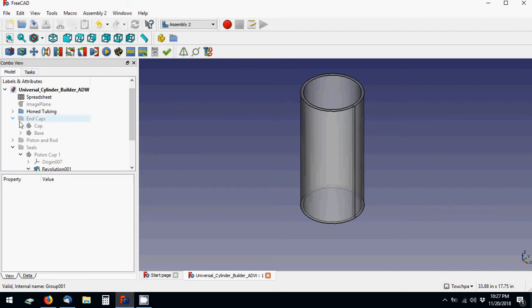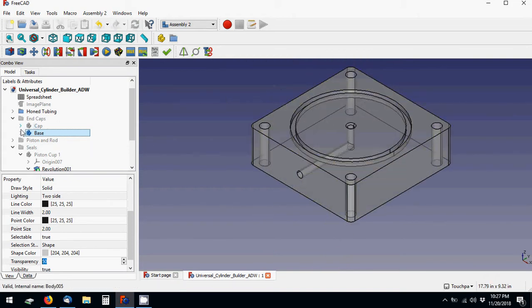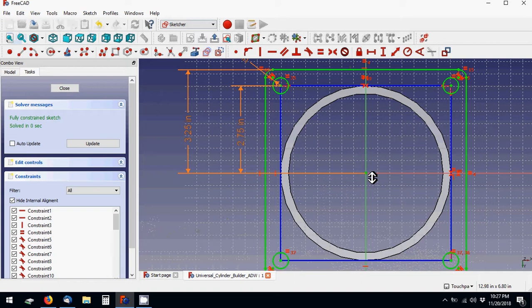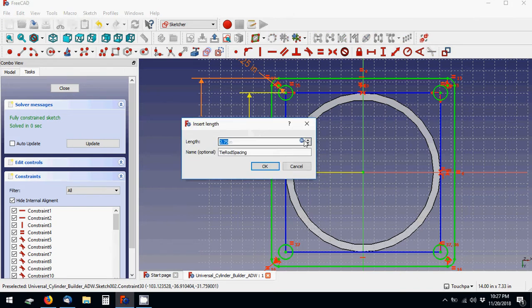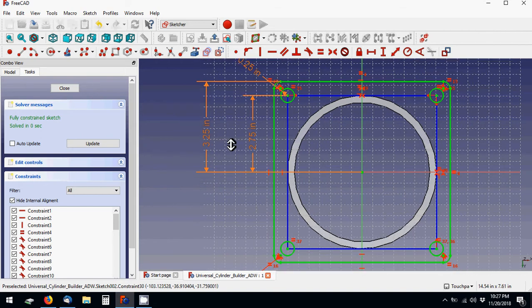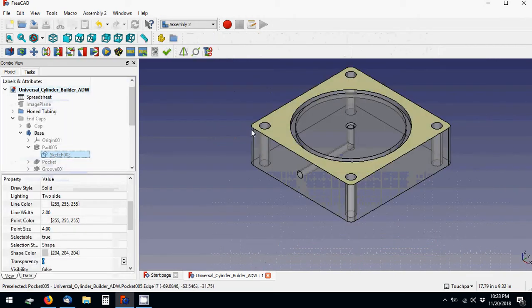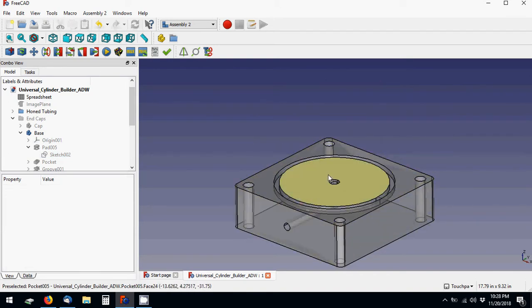And then we move to the caps. The base cap is pretty simple. It's just a square. The circle, the tie rod circle pattern, we use the hole spacing here, and everything is square. It makes things simple. But this hole spacing is equal to the outer diameter of the cylinder. That's just a simple way to do that, and there are others. That may be something that you want to tweak when you generate your model. And then I just gave it a 1/4 inch chamfer, and you set the length of that in your spreadsheet. And then you've just got the bore for the fluid and the trepan groove for sealing the tube. And that's all you need for this end.